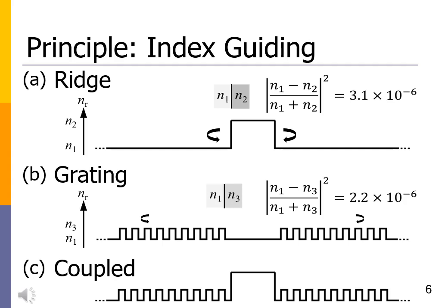The near-field patterns of the horizontal transverse modes are obtained by Fourier transform of the optical spectra. So, a small wavelength difference between the resonant modes leads to a large difference in the peak positions of the near-field patterns. Therefore, the higher-order horizontal transverse modes are located at a region with optical loss while the fundamental horizontal transverse mode exists in a region with optical gain. Please note that the transversal diffraction gratings are used in the total reflection condition. On the contrary, diffraction gratings in DFB or DBR semiconductor lasers are used in the condition far from the total reflection condition.